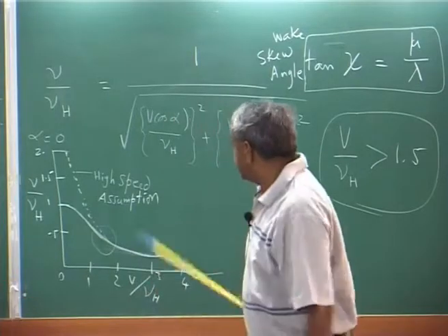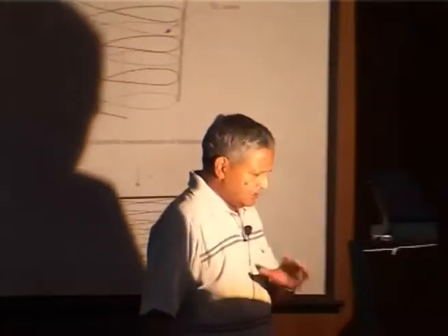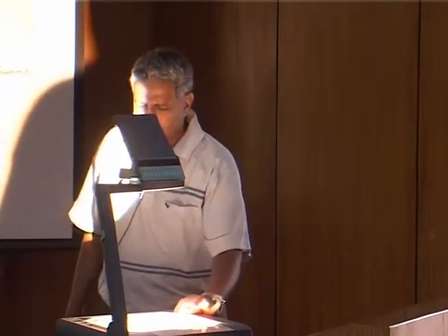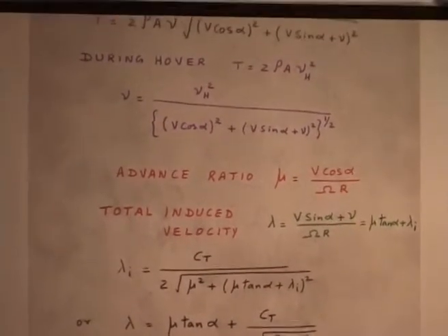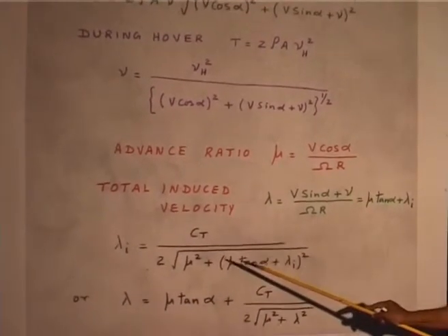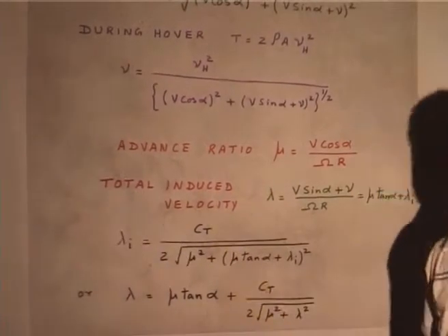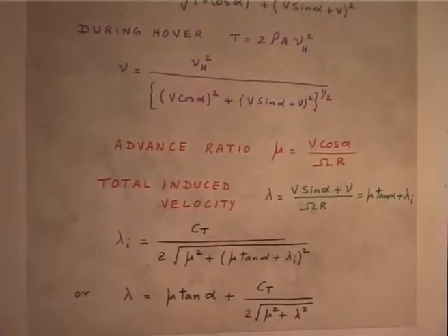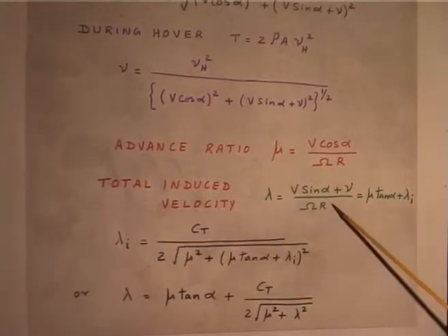But please remember this equation or the earlier expression which I showed you, they are used to get this relationship. Please understand, this is induced flow nu over omega r. Okay, this I wrote last time. This is essentially the equation which you use to get it, but please remember here it is non-dimensionalized with respect to omega r, tip speed.